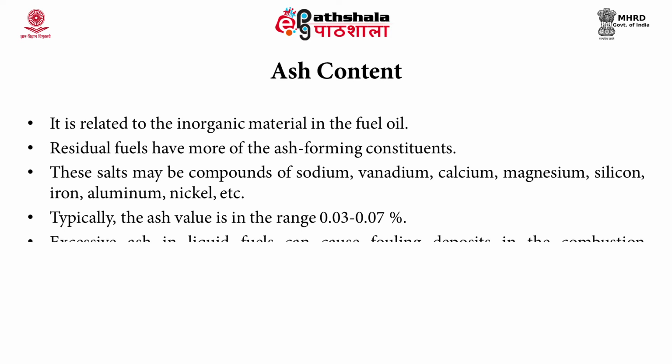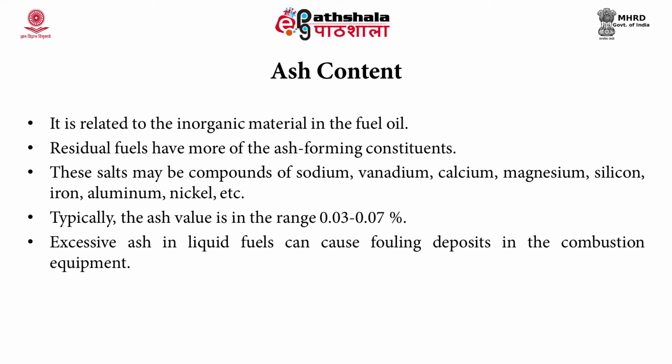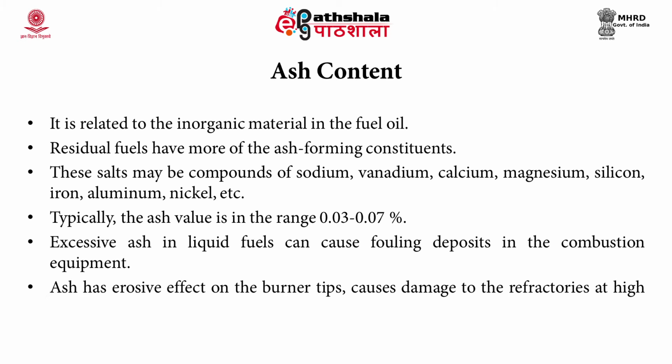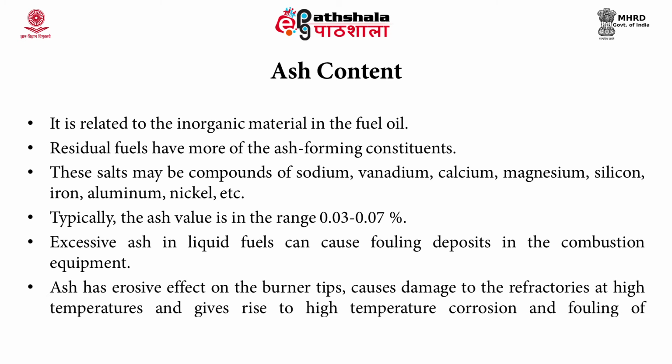If excessive ash is present in liquid fuels, it causes fouling deposition in the combustion equipment. Ash also has an erosive effect on the burner tips. It causes damage to the refractories at high temperatures and even gives rise to high temperature corrosion and fouling of the equipment. Ash content is the amount of inorganic residue present.